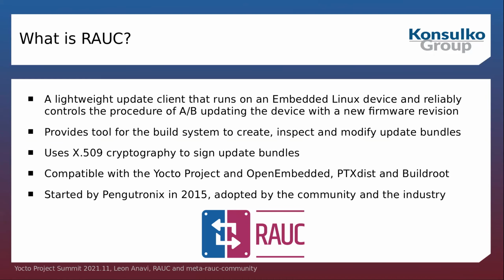The first keyword is slots. The slot is pretty much anything that can be updated with RAUC. In most cases, it's a disk partition, but it could be a physical device or even just a file. The other important keyword in the RAUC ecosystem is bundle. The update bundle is the artifact that's downloaded on the embedded device and installed as an update.